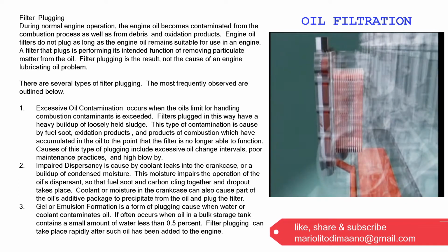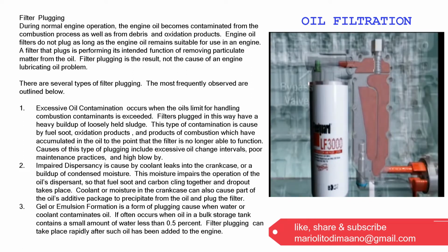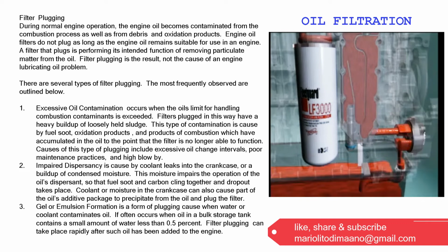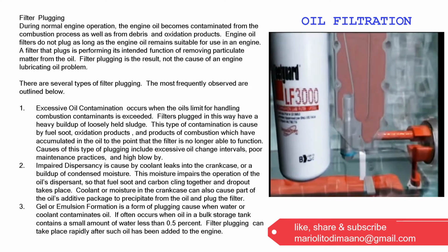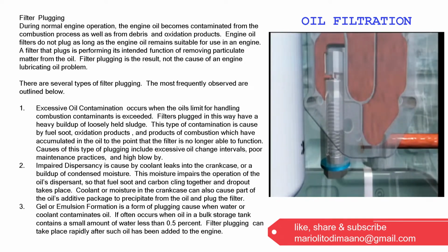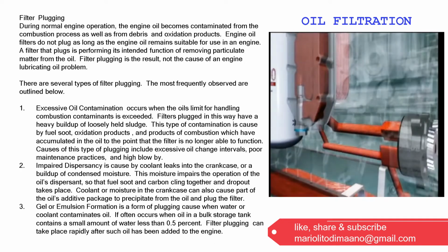This type of contamination is caused by fuel soot, oxidation products, and products of combustion which have accumulated in the oil to the point that the filter is no longer able to function. Causes of this type of plugging include excessive oil change intervals, poor maintenance practices, and high blow-by.